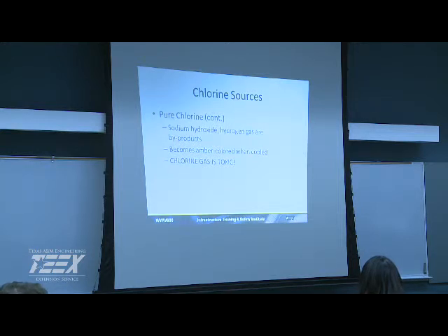And it's important when you're working around chlorine gas that you have the right respirators on, that the cartridges are actually good and not expired, and that you can get out of there if you have a problem. That's real important. And then who's going to come in and do the repairs for you? Who's going to come in and stop a leak? Or do you rely on your local fire department? Most of the small volunteers don't have the training or the equipment. So who's going to do that for you? That's a big consideration.